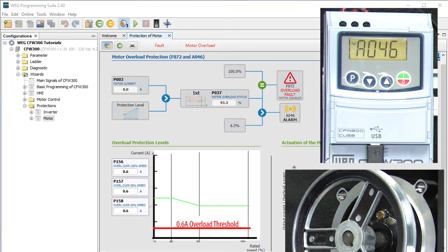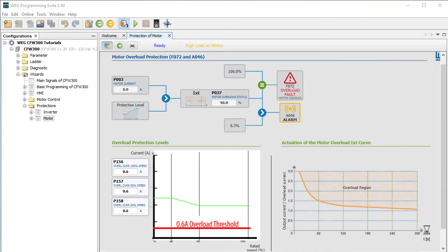Hopefully now you can see that setting the overload curve appropriately is crucial to getting the best possible protection for your system. And that's important to understand. We just did a system overload example. That is, we measured the motor current when the system was under load and then added 10% for the overload thresholds. For us, that was a motor current of 2.2 amps, which is way below the motor's 3.2 amp ability. We weren't trying to protect the motor here, we were protecting the system.